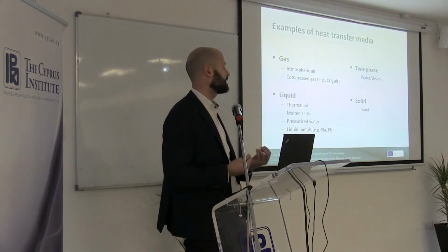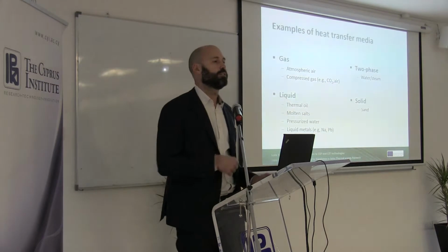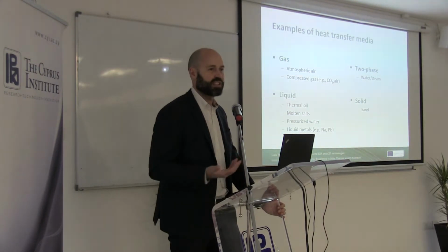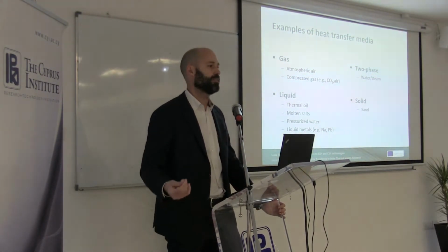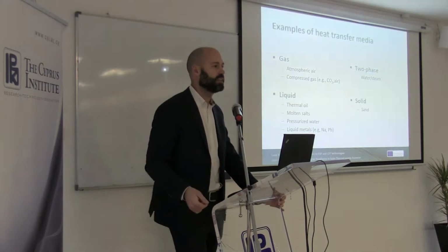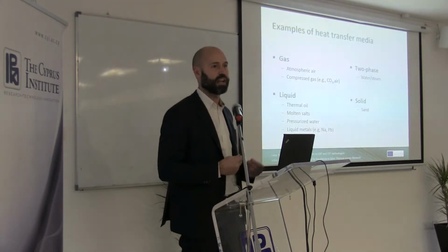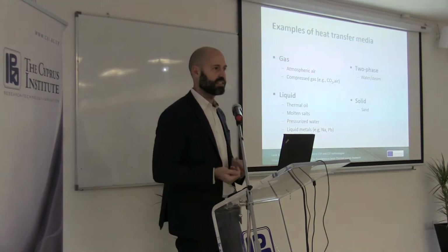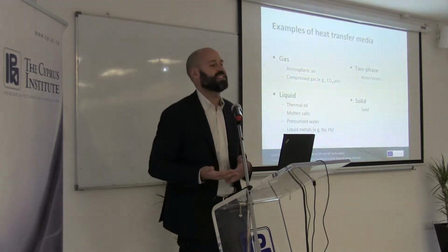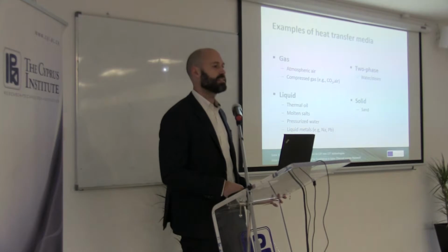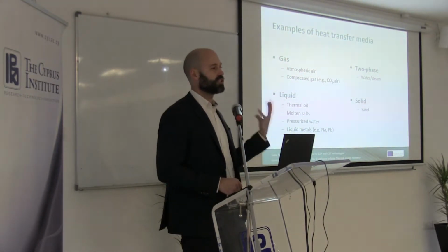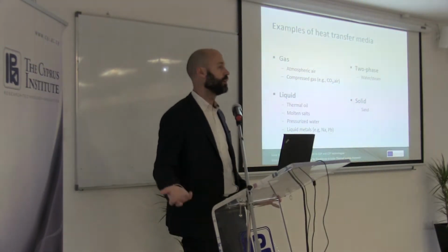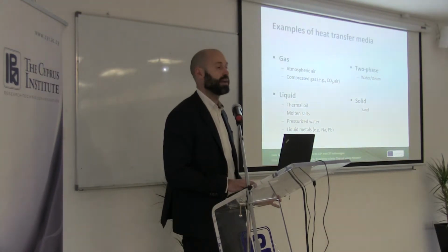How do we use solids? Like sand or granular solids, which are fluidized and sent to the receiver. The advantages in this case are clearly that they are cheap, they are safe, and we don't have freezing problems, but at the same time there are other types of issues like friction problems on the surfaces and so on. Also, it's not that easy to move these solids around the plant, at least it's not as easy as moving a liquid or a gas, as you may easily understand. So the research in this field is very active, even if, again, these other heat transfer fluids are not implemented in commercial plants.